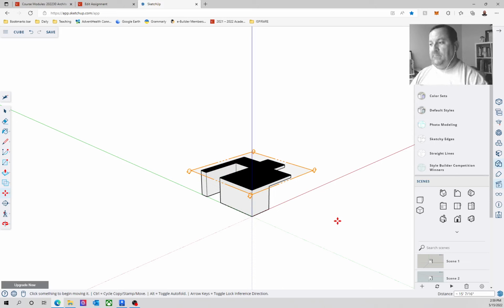I prefer plan cuts. Well, in real life, if you're drawing a plan of a building, these horizontal sections that become plans are in fact somewhere between 30 to 40 inches above the ground plan or the level line that you're dealing with. So in this case, this is a 24-foot model. So we're going to come down to about a third, which is about 16 feet below the top, which is 24 feet. So it's roughly an 8-foot section cut. Okay, so that's in general what a plan is: a horizontal section cut.